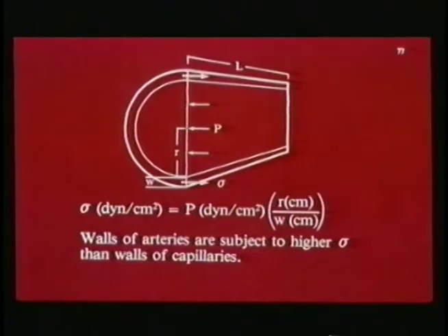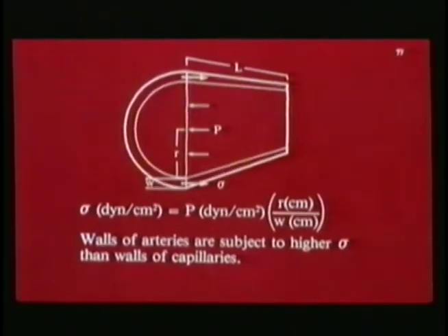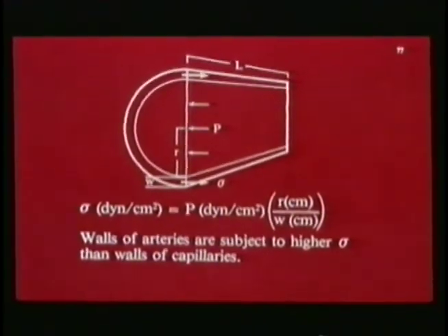The walls of arteries are subject to higher circumferential stress than the walls of capillaries. This is mainly because of higher arterial pressure. Although the capillaries have much smaller radii and thinner walls than arteries, the radius to thickness ratio does not differ dramatically between capillaries and arteries.